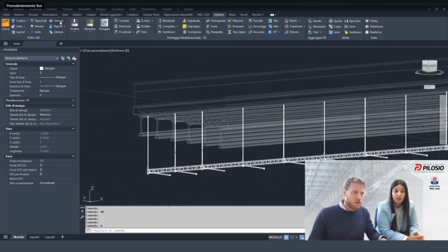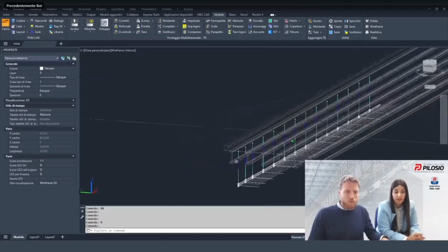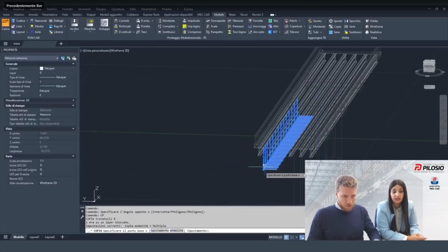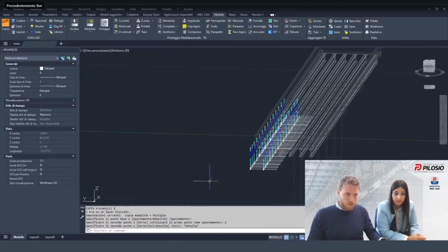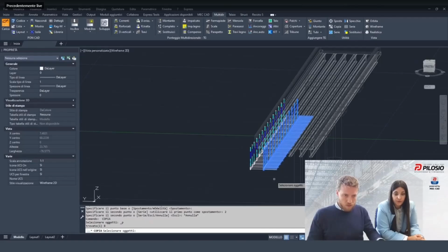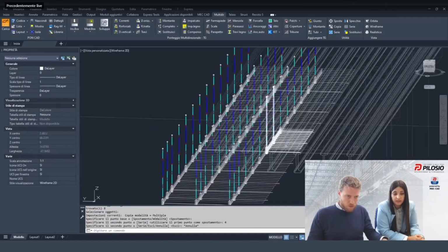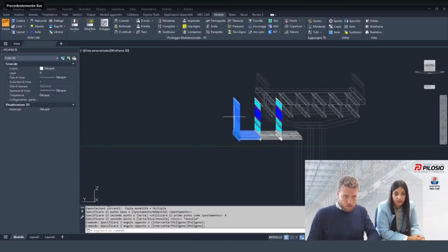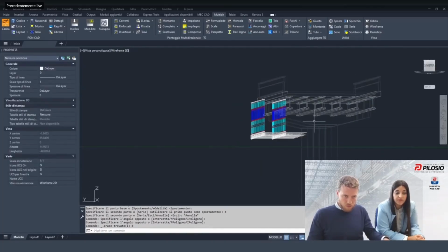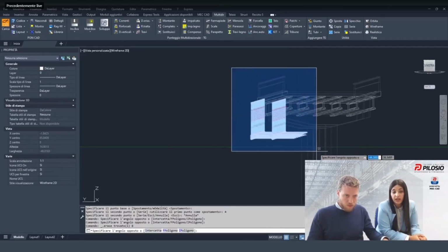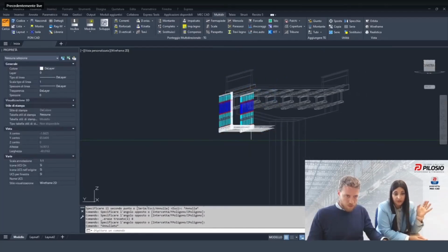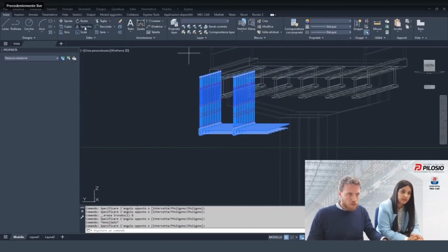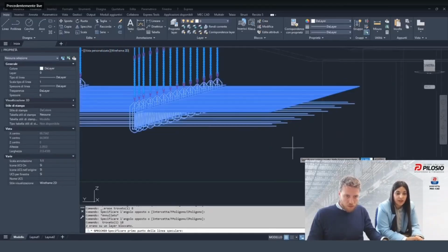Yes. When we checked that everything is perfectly set in the right place, now we can just copy and paste and erect the entire fly deck. We will copy 2 meters on each side, and then it's enough to use the command mirror just to erect the other part of the bridge. In this case, we will have 2 meter steps on the side and a 2.5 meter step in the middle, so it will be easy to bypass the abutment.